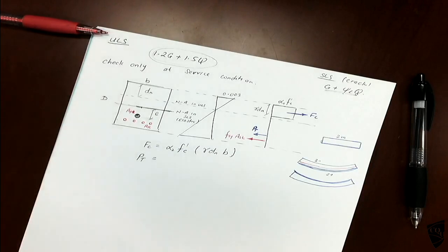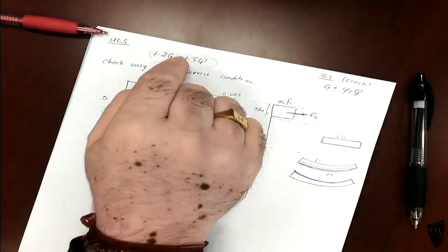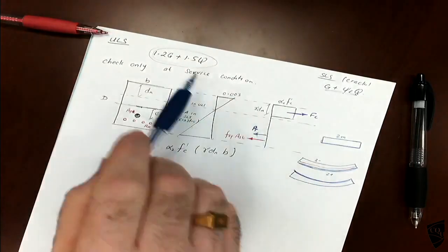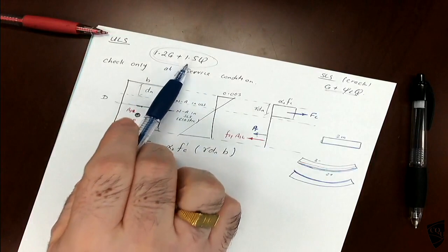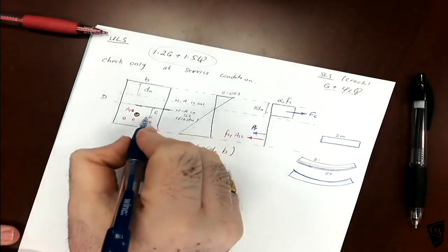So when you stretch the steel, what will happen? That will give more compressive force, because when you stretch it under tension, it tries to give more and more compressive force. So the pre-stress force at ultimate will be larger than what we calculated earlier. You can't use the same pre-stress force here.